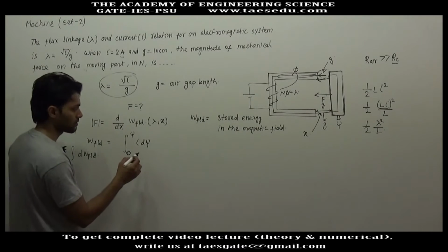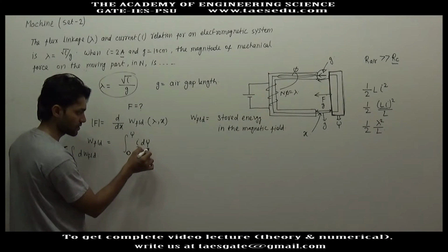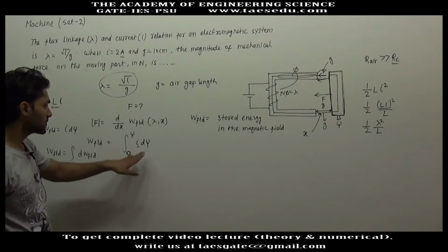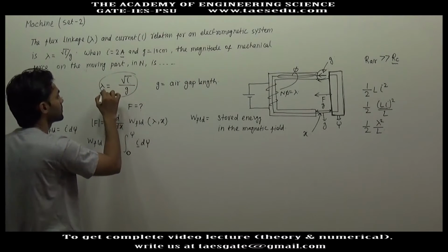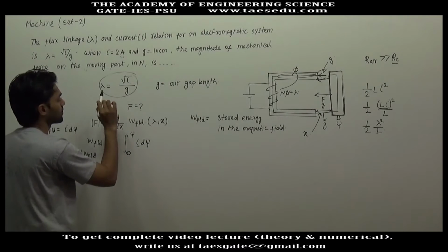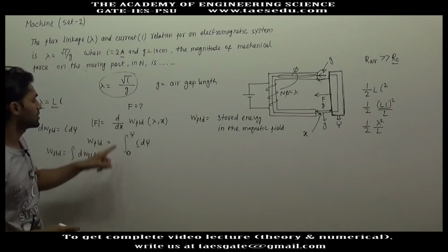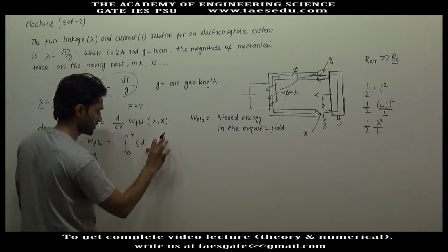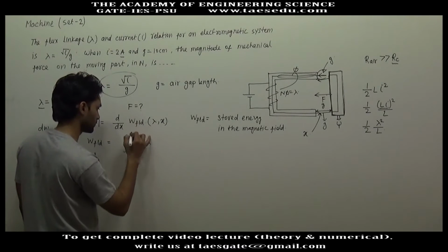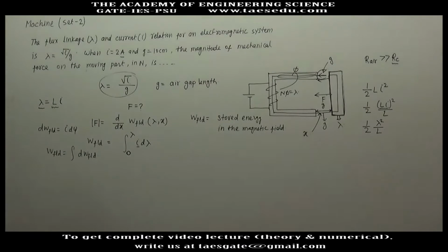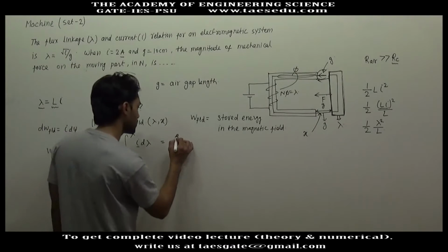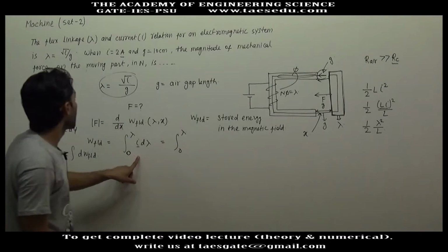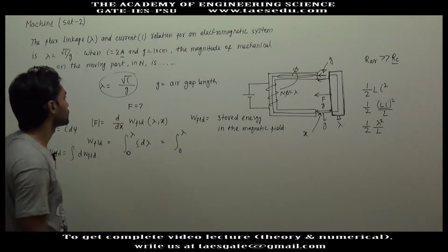where i is also variable and psi is also a variable, and we have a relationship between i and psi, the total flux linkage. In this question, the total flux linkage is represented by lambda. Okay, so we are first finding the total stored energy. This will be 0 to lambda, and i and lambda are related. What will be i?